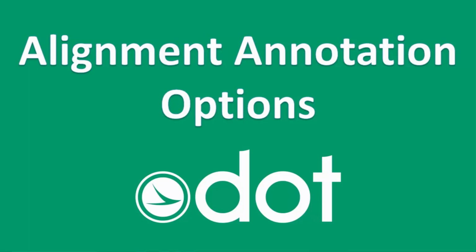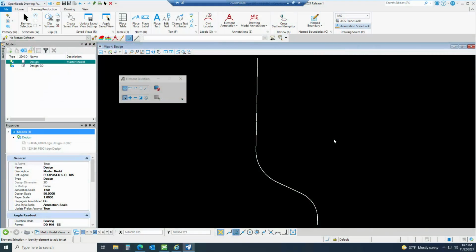Let's take a look at annotating an alignment using OpenRoads version 10.10 and the Ohio DOT CADD Standards. So we've made a change to the standards for version 10.10 to take advantage of a new function. In previous versions, when you used the annotate element command, you would select the element and reset to complete your selection, and the element's annotated.